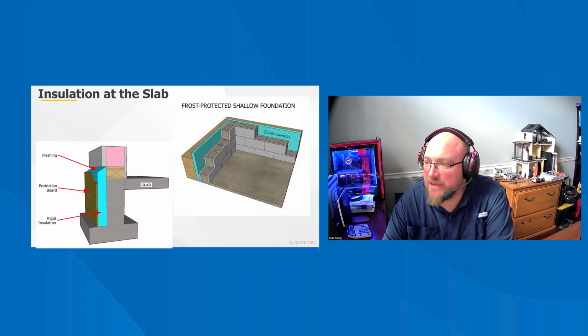installing exterior slab perimeter insulation is to use a frost-protected shallow foundation. These foundations are found in northern regions. They are most cost-effective in climates where required frost depths are substantially greater than 12 inches and foundation insulation requirements are more stringent. Frost-protected shallow foundation systems offer a design option that allows for shallower footing depths by raising the frost depth around the building through the use of insulation.